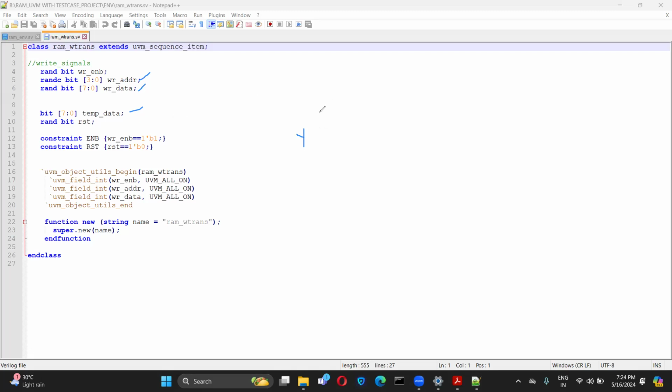A value is 2 and B value is 3, so Y will be 5. If you randomize this Y also, then that will override the result which we are generating, right? That's why we need not randomize the output value, and we should only randomize the input values.